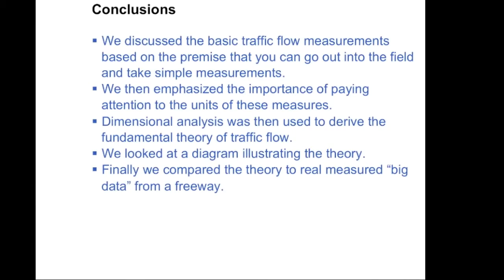So in conclusion, we've discussed some basic traffic flow measures based on the idea that you can go out into the field and take some simple measurements. You could do this yourself. The importance of paying attention to the units of these measures was emphasized. We used dimensional analysis to derive the fundamental theory of traffic flow. We looked at several different diagrams for illustrating that theory. And then lastly, we looked at some real data, you might call that big data, from a freeway, and briefly discussed how those matched the theoretical foundations.